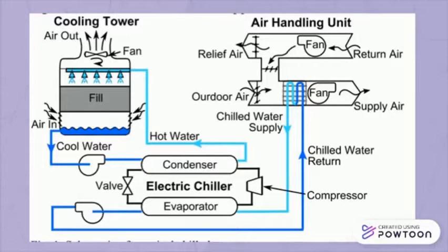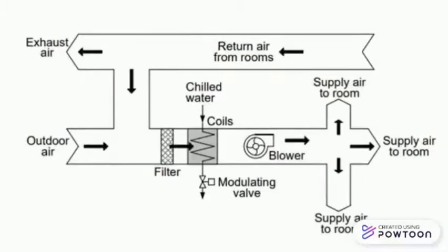On the other hand, the condenser water pump circulates water through the condenser and the cooling tower. The heat absorbed by the refrigerant in the evaporator and the heat added to the refrigerant by the compressor are rejected to the circulating condenser water as latent heat of condensation. The warm condenser water then flows to the cooling tower and rejects heat to the ambient air. Cool condenser water is pumped back again to the condenser and continues the cycle.